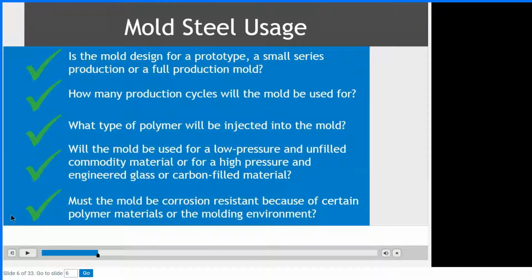We have materials that are not so much used anymore in this industry, like PVC, for example, it's highly corrosive when we process this material under high temperatures, and that's when we really need corrosion resistant steels for the mold. But for most parts, the medical industry always likes to go with stainless steel as well. So let's keep going.